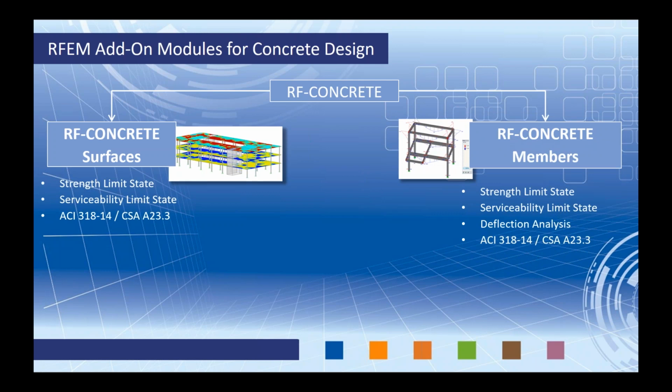The second module is RF-CONCRETE Members. This allows you to run, again, both strength and serviceability limit state design. We can include deflection analysis here for serviceability according to the ACI, CSA, and international standards for 1D members, so beams and columns.